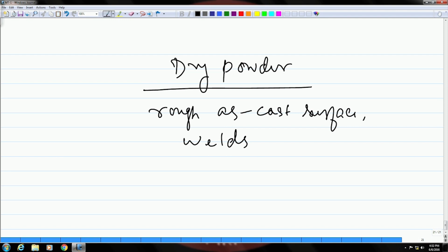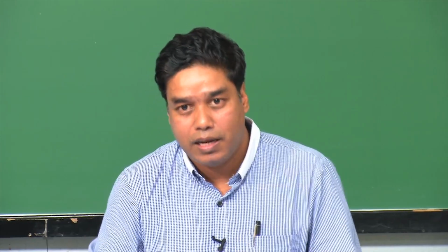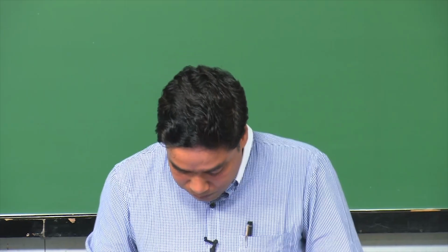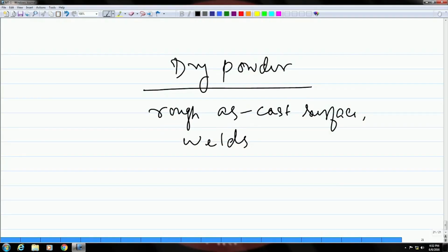If you do the inspection, the weld is very rough. So, there again dry particles are useful, and they are also used for shallow subsurface cracks.